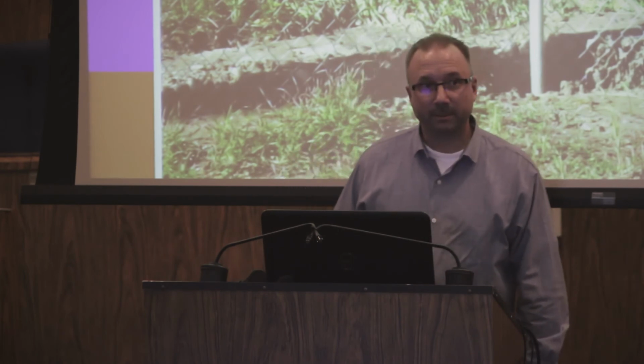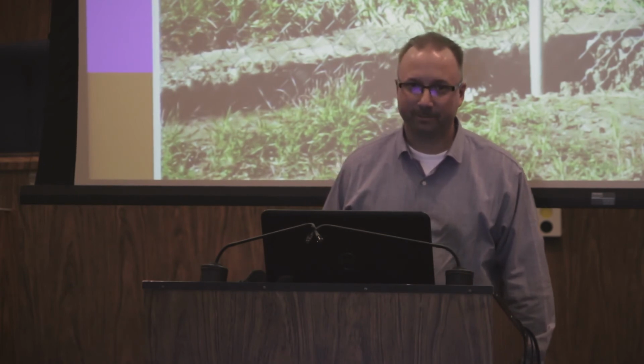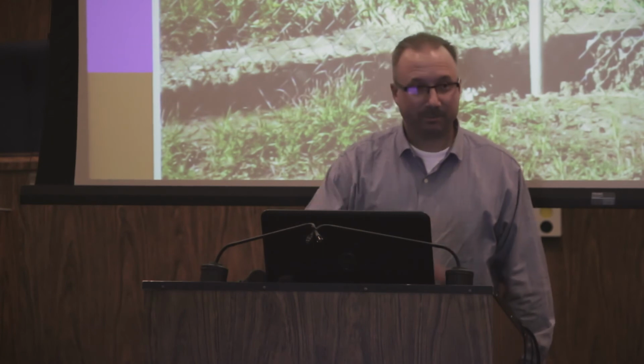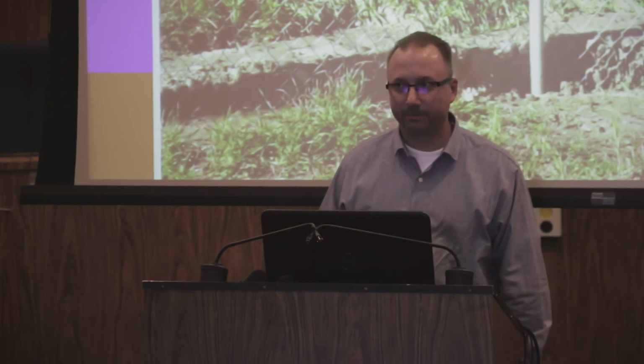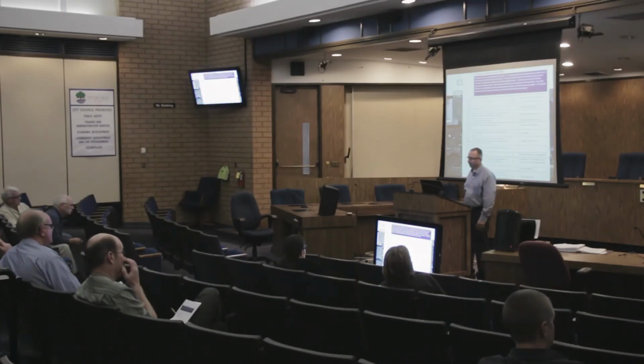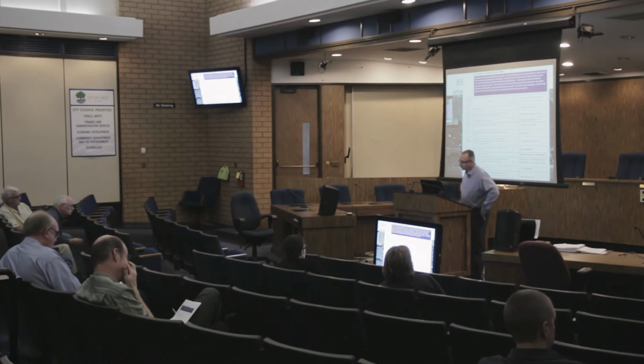Did that fence filter that sediment? No, it didn't filter it, did it? It slowed the flow enough, just enough. I mean, I took that picture myself. Enough to slow it out. So it's not about filtering, it's about slowing the flow. That's what sediment control is about. Now, this sediment was just begging to fall out, and it just needed something like chain link fence to give it an excuse. And certainly much went by that should not have gone by, but nonetheless, that illustrates what we're talking about here.